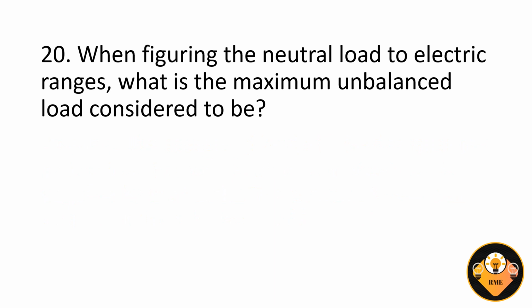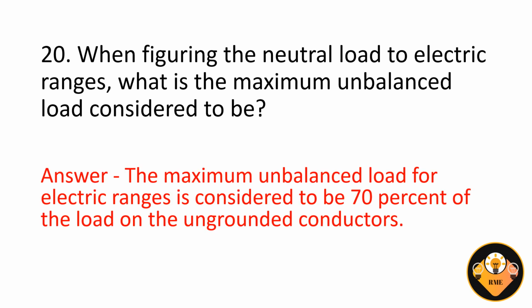Number 20. When figuring the neutral load to electric ranges, what is the maximum unbalanced load considered to be? The answer is, the maximum unbalanced load for electric ranges is considered to be 70% of the load on the ungrounded conductors.